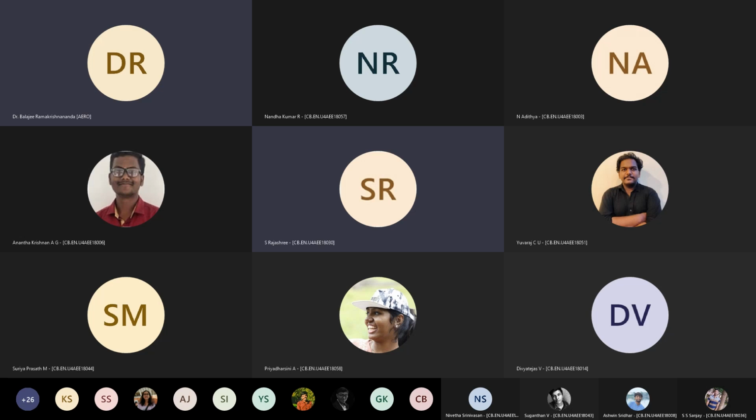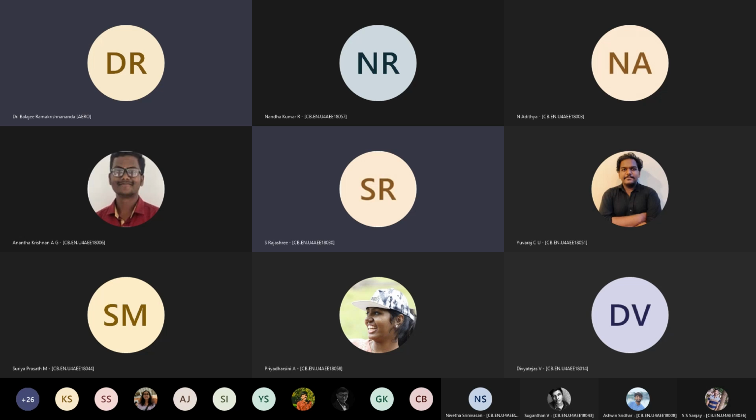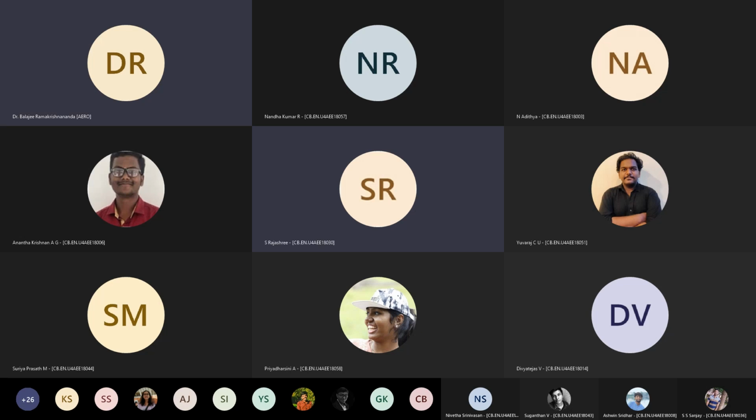Yes, sir. You said that it's not reliable to use that data to find out the region of stall, right? Then how do we know till what range we can actually consider? So how will I know if my airfoil has a huge stall range or not? You generally assume it over predicts stall by 2 degrees. Okay. XFOIL over predicts stall.